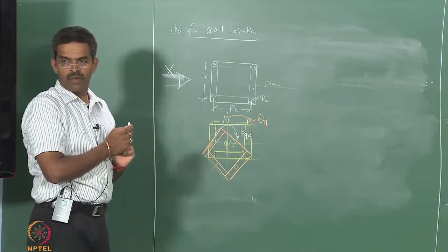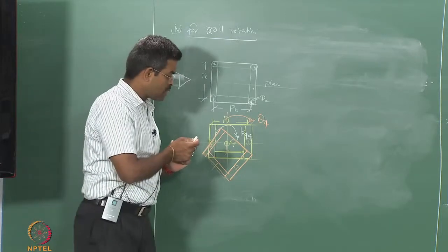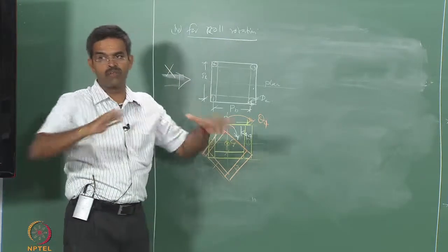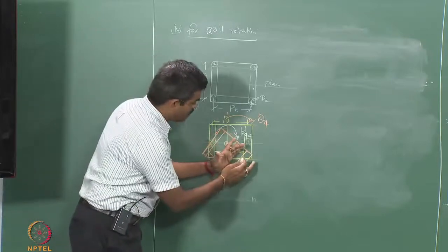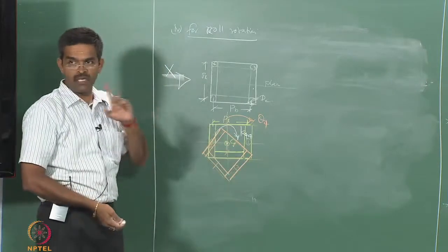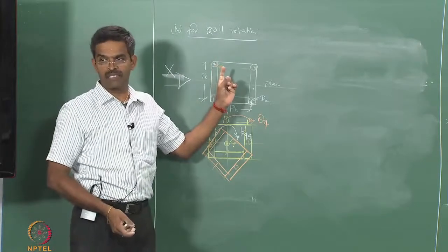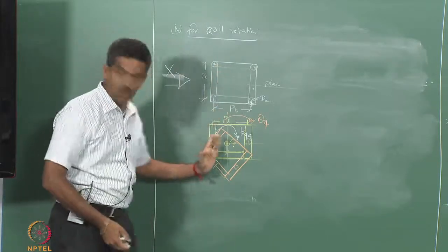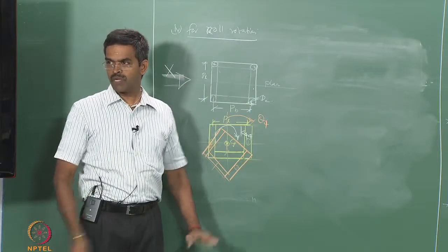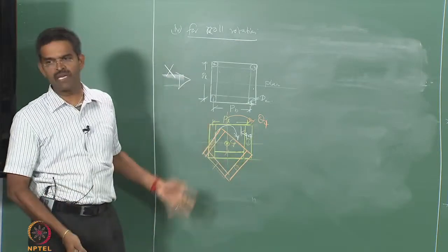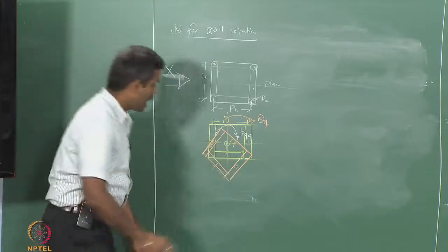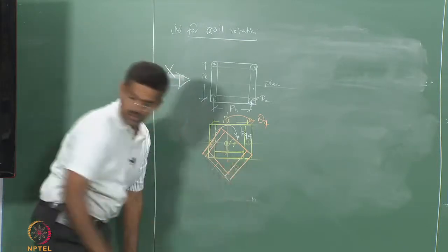Now obviously you see column 1 is submerged more compared to column 2. Buoyancy force is nothing but an upward force acting on the submerged volume of the member. The moment the member is submerged more compared to the other one, initially the buoyancy was coplanar and collinear with the center of gravity for static stability. It will now move towards 1, because 1 is submerged more compared to 2. 2 is lifted up as per this configuration. So I mark the new value of FB.